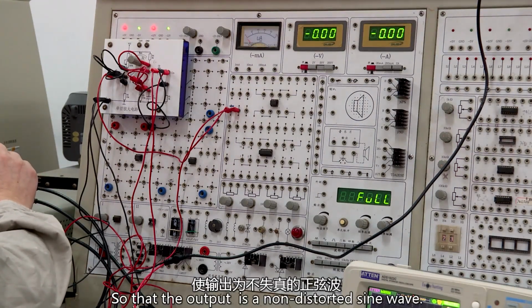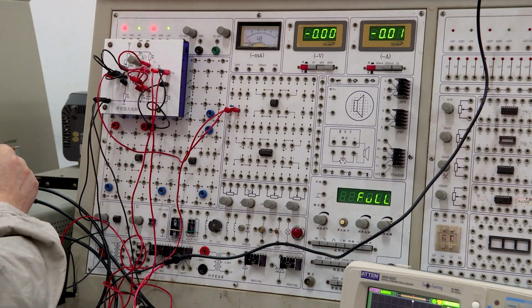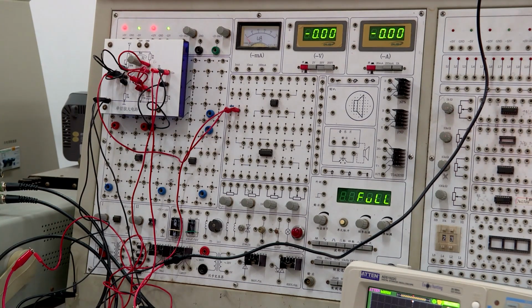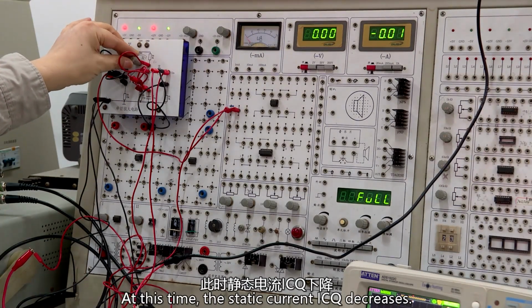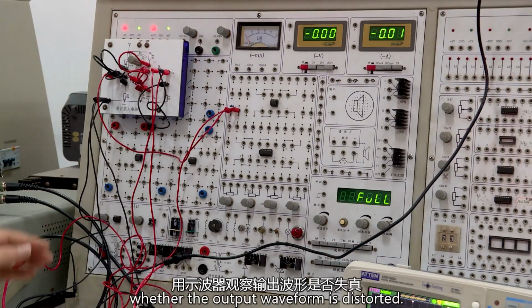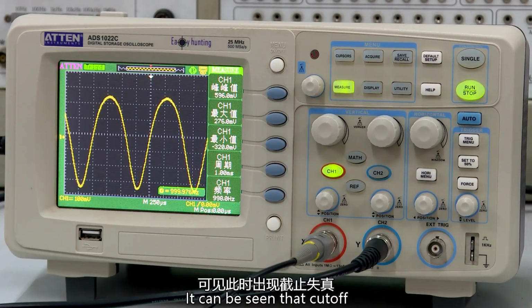Adjust so that the output is an undistorted sine wave. Set the resistance of the potentiometer RP to the maximum. At this time, the static current decreases. Use the oscilloscope to observe whether the output waveform is distorted. Draw the waveform at this time. It can be seen that cut-off distortion occurs at this time.